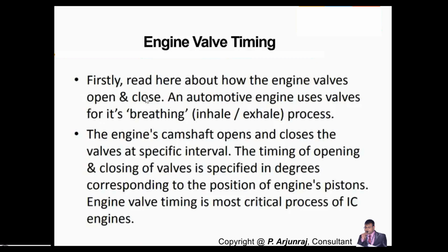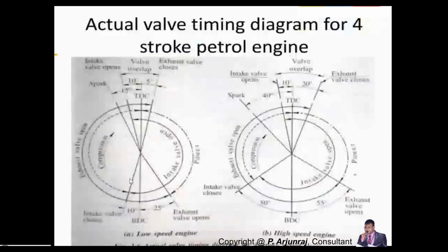Here the engine camshaft opens and closes the valve at a specific interval, and the timing of the opening and closing of valves is always specified in degrees, corresponding to the position of the engine piston. Engine valve timing is very important and a critical process in the case of an IC engine, and it also ensures the power and torque of your engine. We will see the valve timing diagram. First, I will complete the four stroke, then I will come back to the two stroke.